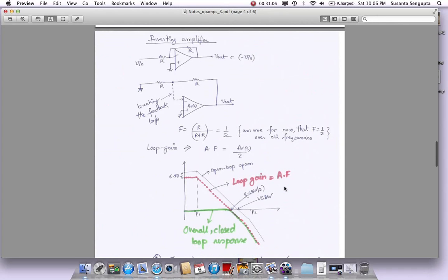Another example that I will go through, the second example, is an inverting amplifier, and this is where I think it will start getting more and more interesting. So this is where I'm trying to show an inverting amplifier where we have V in and V out here, and these are two equal resistors. They don't have to be equal, they could be in any ratio which will give you the gain, but I've just kept them equal to get a very simple transfer function, which is V out is minus V in. The positive input is normally AC ground, at some fixed DC voltage here.